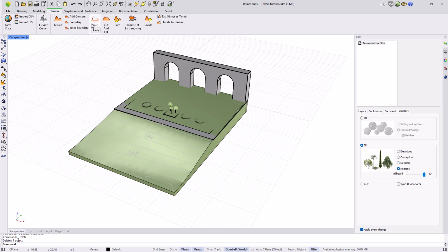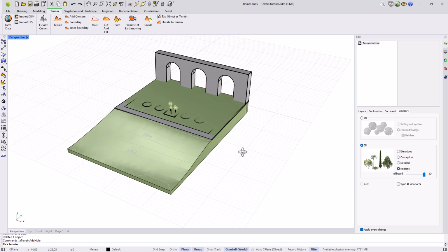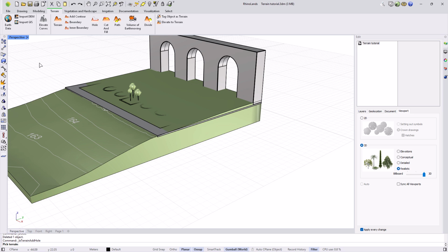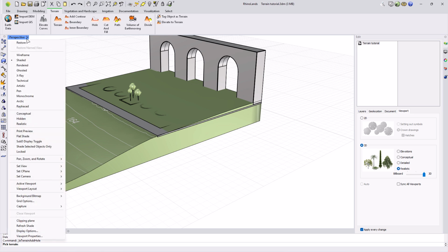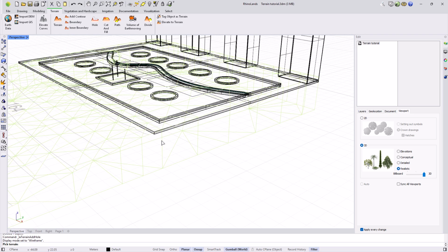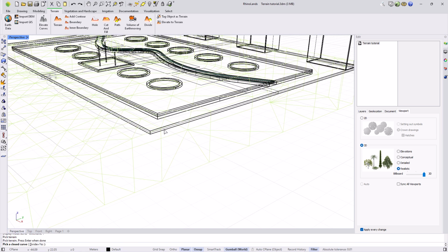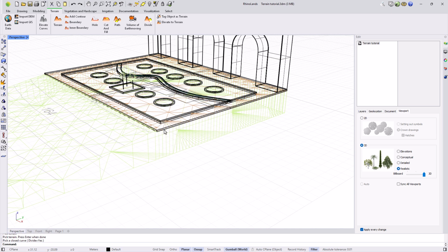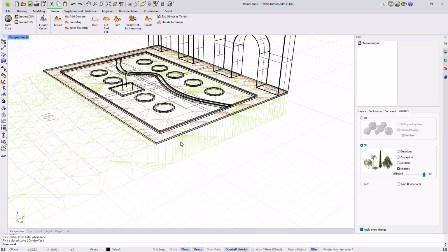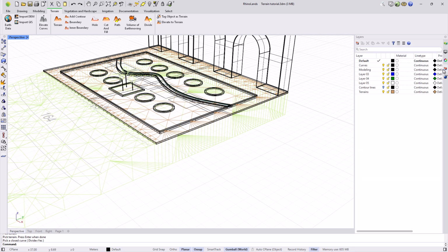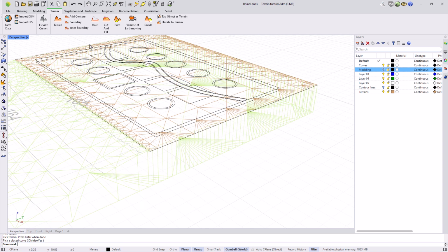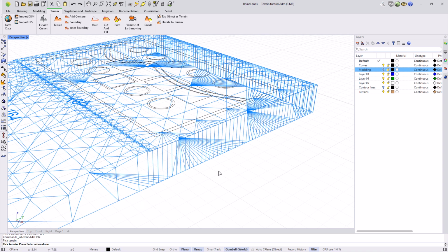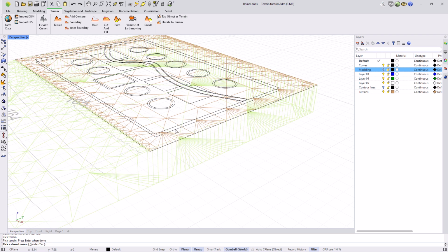The hole tool creates holes or depressions in the terrain by removing material from specific areas. The hole is created from a closed curve that defines the area to be subtracted. In this terrain, I can subtract the contour from the previous modeling to flatten it out and at the same time, remove the thickness of the pavement. We need to have the curve created beforehand, and now I can select the terrain and the curve used.